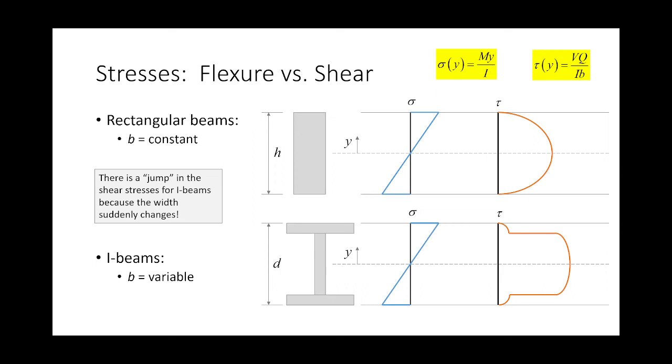Now, bending, sigma equals My over I. That doesn't change dependent upon the type of cross-section that you look at, but shear does, okay? What you find is that our expression VQ over IB is the means of determining transverse shear stresses across the section, okay? Now, if you want a very simple explanation for what's going on, here's what's going on.